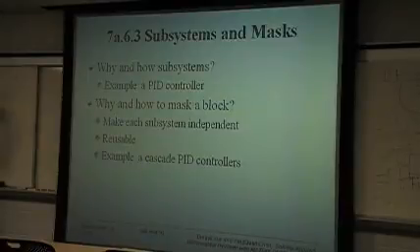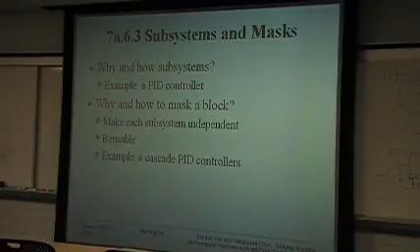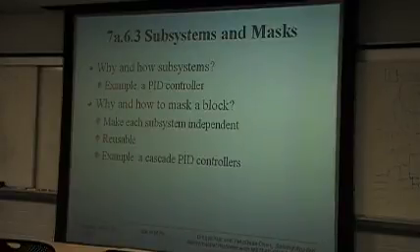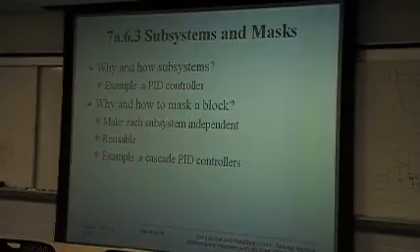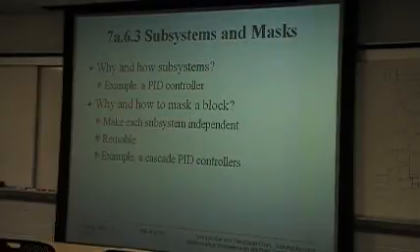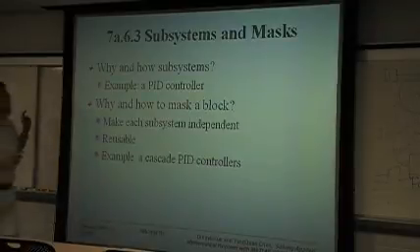If you draw all of these in the same window, it is far too complicated to recognize which is which. So the best way is to group the controller together as one block and group the plant as another block. This is what is called subsystems. So you can make the whole structure of the system easier.